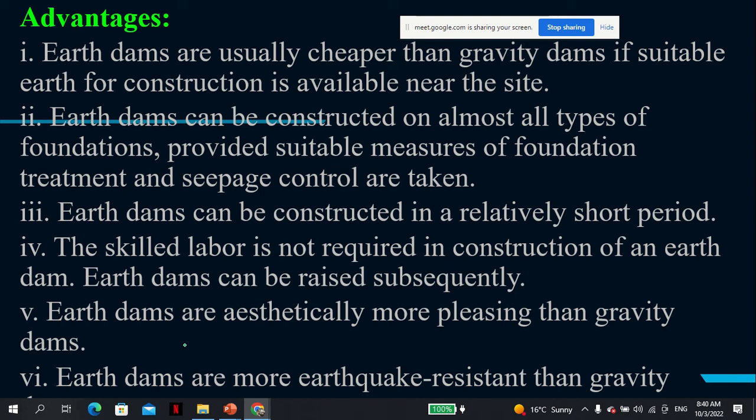Rigid structures can take very little strain and they snap or they crack, and this is why concrete is prone to cracking. But earth dams can take high amounts of deformation, and as you know, earthquakes will induce some deformation. So this is an advantage. In fact, during an earthquake, you need something that can take the forces, can bend or be flexible as it carries the loads, of course, without breaking or compromising the integrity. That's the point. Because concrete is rigid, with some strain, it easily snaps or cracks. But earth dams are a little bit more flexible or less rigid, so to speak.